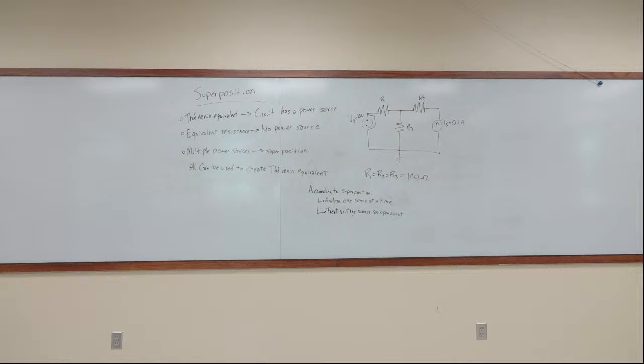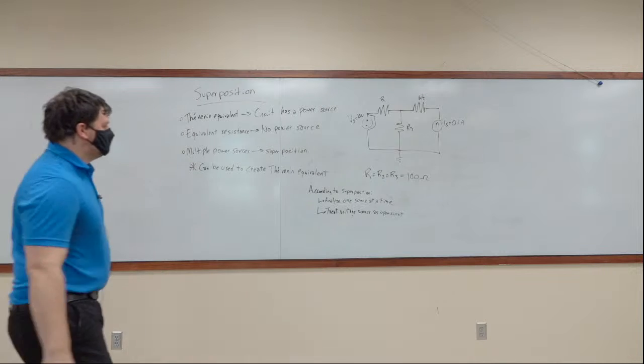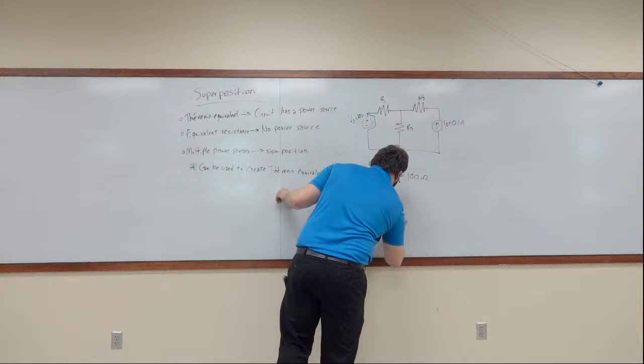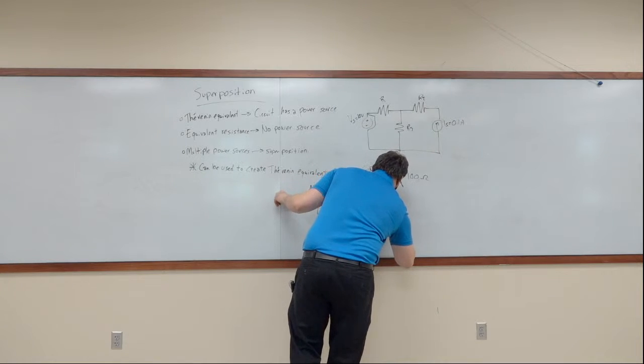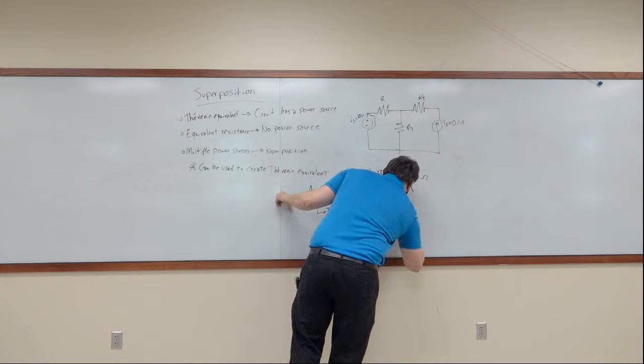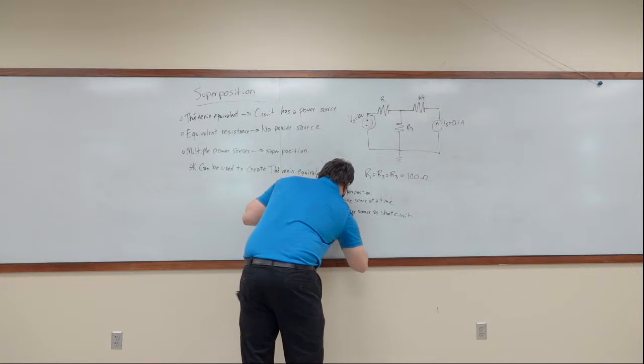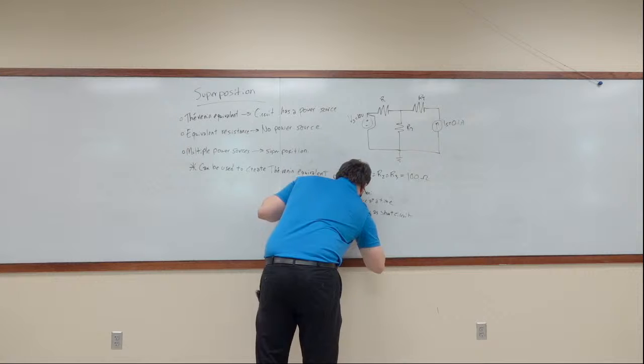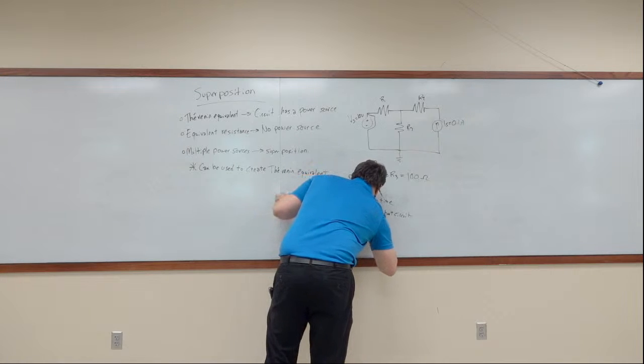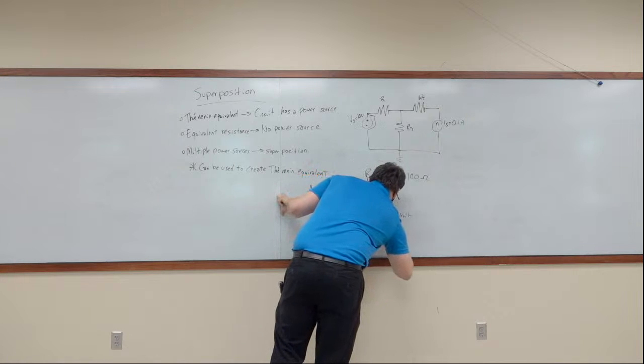Oh no, I am actually wrong. We treat a voltage source as a short circuit. Okay, and then we treat a current source as an open circuit.